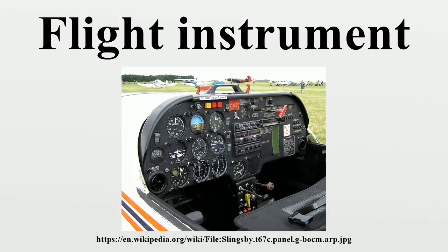It is used for orientation, tracking to or from a station, and course interception. Non-directional radio beacon. The automatic direction finder indicator instrument can be a fixed card, movable card, or a radio magnetic indicator. An RMI is remotely coupled to a gyro compass so that it automatically rotates the azimuth card to represent aircraft heading. While simple ADF displays may have only one needle, a typical RMI has two, coupled to different ADF receivers, allowing for position fixing using one instrument.